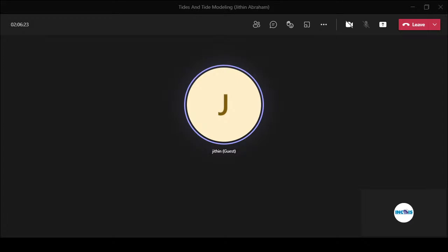How do you validate the results? I think this question means how to validate the model simulated tidal currents or internal tides. The best way is to compare the constructed tidal ellipse for both barotropic and internal tides, and compare the semi-major axes, minor axes, inclination and phase. That way you can validate it.